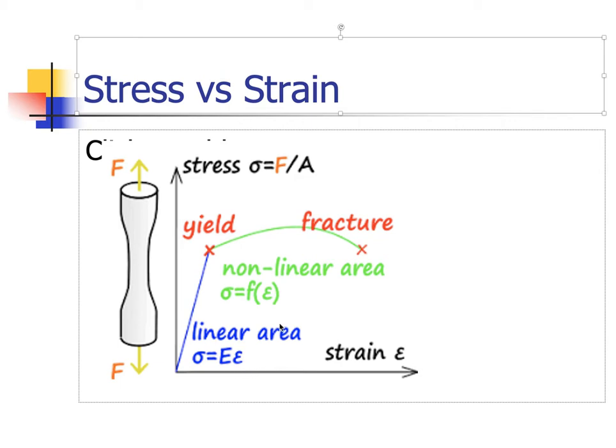Now, what happens is, with metals, if it's a brittle material, it's going to load to this point and it's just going to fracture. We're not going to have any elongation where it gives us a warning. Now we know that if we have a rod or a bolt or something like that, even the stainless steel here, I don't know if I can pull it again, but if I take a piece of this, I've got to get it around my fingers. I don't know if I can.